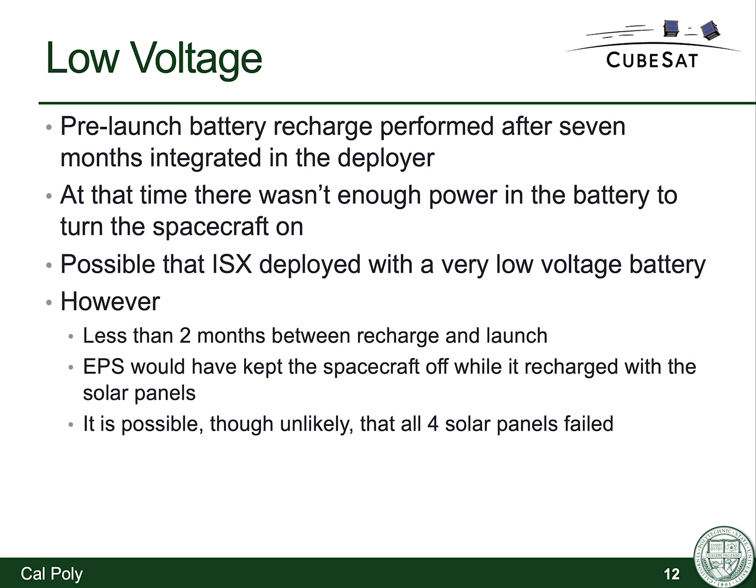Another potential failure is that the spacecraft just didn't have enough voltage in the battery pack in order to boot up. We felt it was important to investigate this failure mode because we went back and there was a window when we could recharge the spacecraft, recharge ISX, prior to launch. It had been integrated in the dispenser for about 7 months, and then due to various schedule delays, we were allowed back in after 7 months to recharge it, approximately a month or two before it launched. When we came back and recharged it, the batteries were totally dead. It didn't have enough voltage to boot. So in that 7-month period, the battery managed to drain itself.